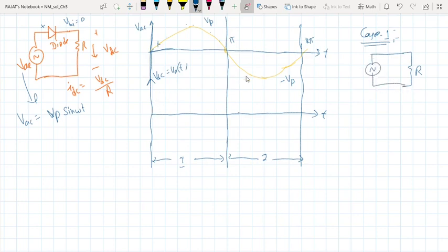Okay, so what voltage is experienced by the resistor? It is directly the source voltage. Okay, the output voltage looks like the source voltage. So what will happen, the voltage waveform is just like the input. Okay, in case 1. In case 2, a negative voltage you are applying. That means if here is a minus, then what will happen, the diode will turn off. If the diode turns off, then the diode acts like an open circuit.